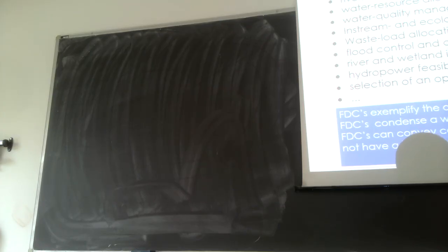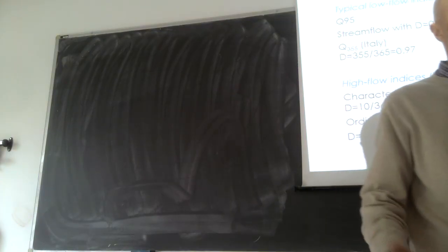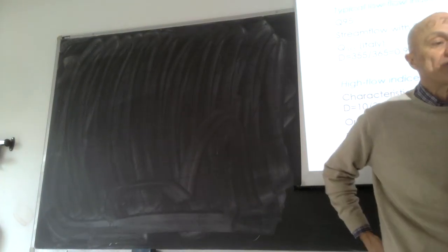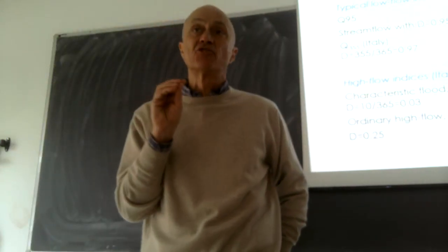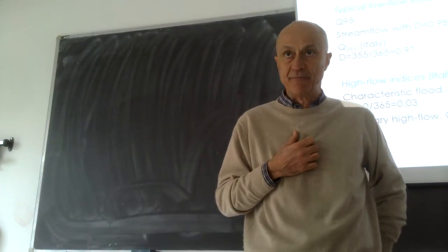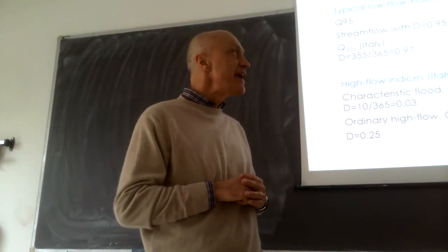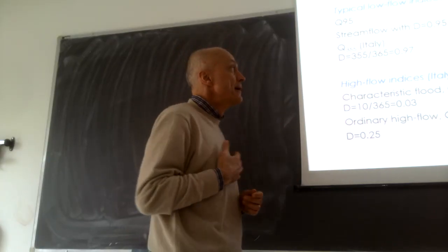Okay, let's come to very classical uses of flow duration curves. Now, flow duration curves worldwide are used for characterizing stream flow regime in natural streams and rivers, okay? In various nations, there are various classification, let's say, criteria, but based on stream flow, we can depict, represent what flood flows are, high flows, intermediate, and low flows as the duration moves towards higher values.